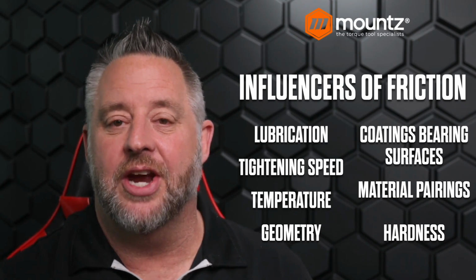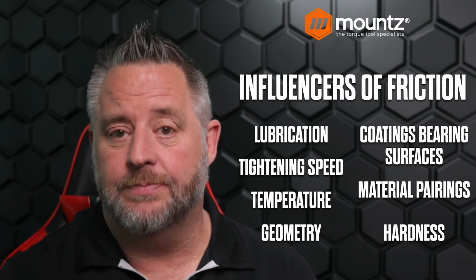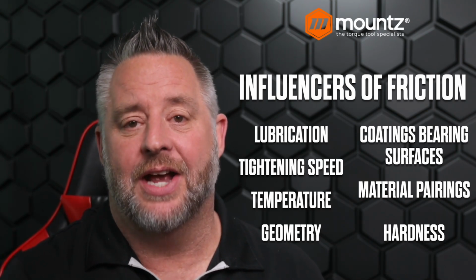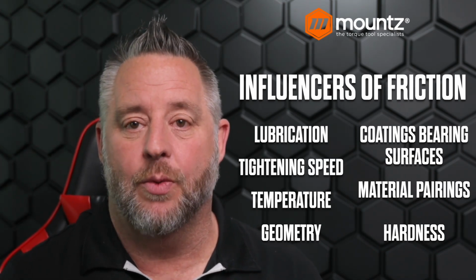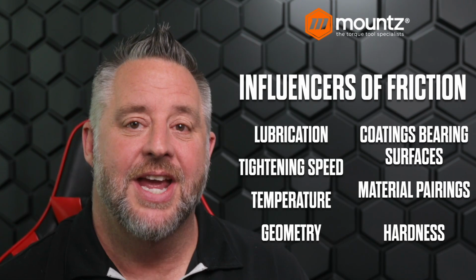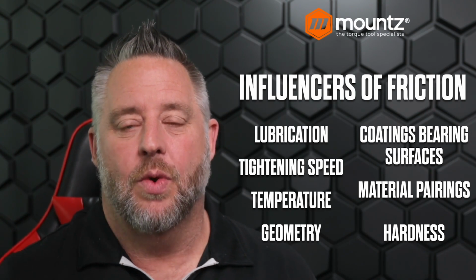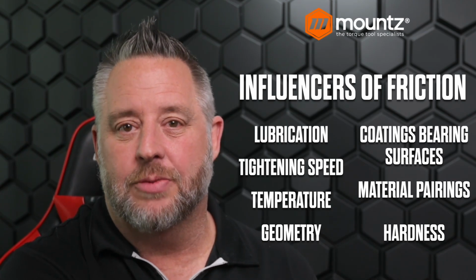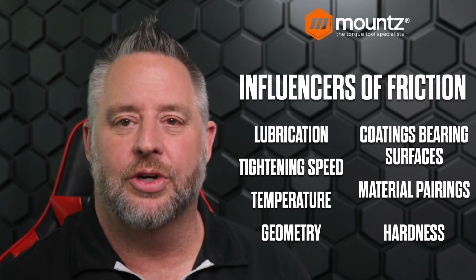And then again, if we change the geometry or the size of a washer or a fastener, that can play a part in the frictional output, as well as the hardness of a particular material, if that again is not what was used when the torque specification was originally spec'd. So these are some of the areas where the frictional forces can cause a tremendous amount of change in the final clamp load, which is what we're trying to achieve.